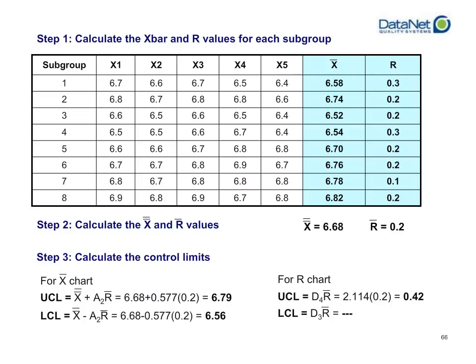Now that's just the control limits for your primary or upper chart, your X-bar chart control limits. Your R chart is going to have its own set of control limits. In this case, you have an upper control limit for your possible ranges. And in this case, it's going to be D4, which is a constant, again, from a lookup table, times your R bar value that you calculated in step 2. And that's going to give you your upper control limit.